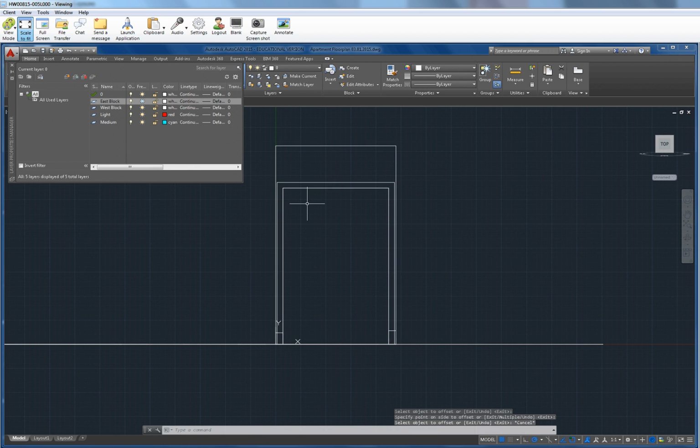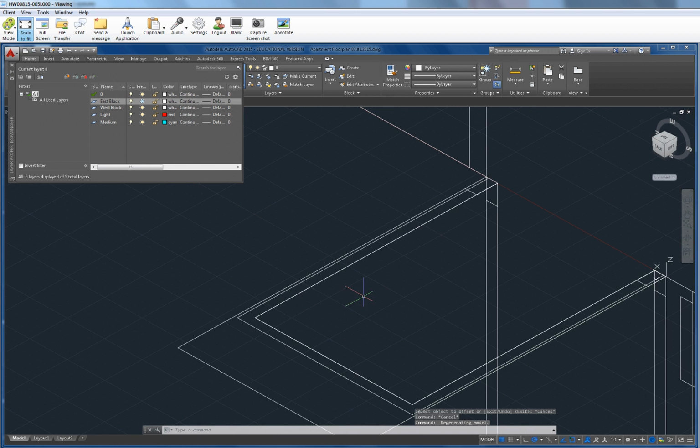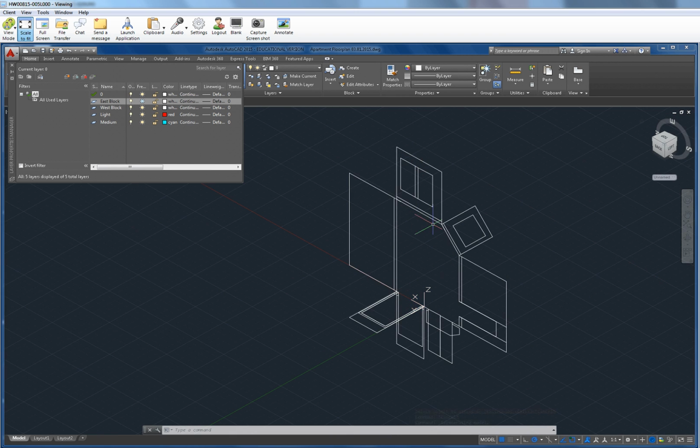So if I offset something and I draw something there, I know it's going in the right position, right? And if it wasn't, if it was just Z somewhere that we didn't really control, it's based off of where Z world 0 is, it would draw it over here, you know, somewhere else. And then we can move it. I mean, it's not a big deal to fix that, but it's one extra step.